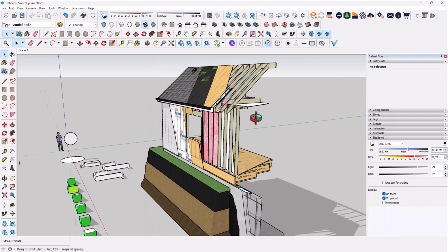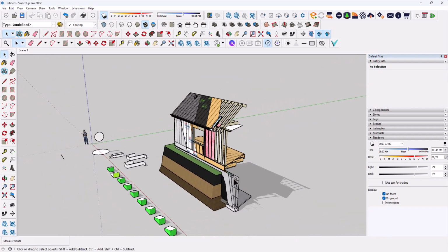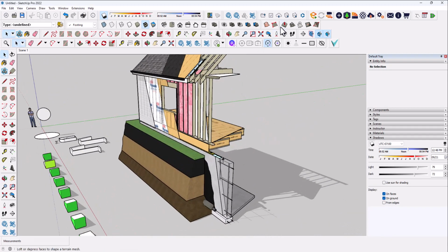One more thing to show, and this is useful for architects, product designers, the section tool. So the section plane is here, and you'll notice that it's trying to find an orientation. Again, I can use the arrow keys on my keyboard to choose the orientation. So I want to cut a section through this project.